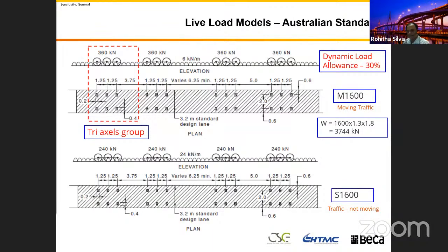If I tell you 2 lanes is equal to 760 ton, it's a little bigger than an A380 aircraft weight, because I know that an A380 aircraft has 24 wheels, every wheel has an axle reaction of 30 ton, 300 kilonewton.